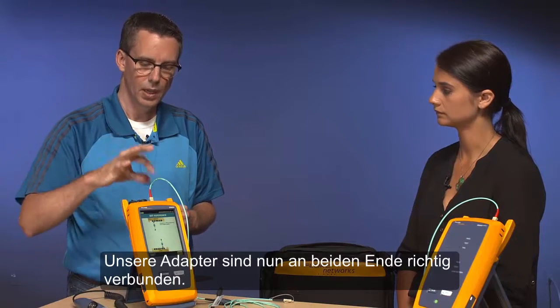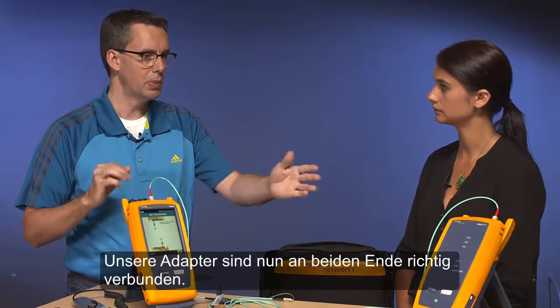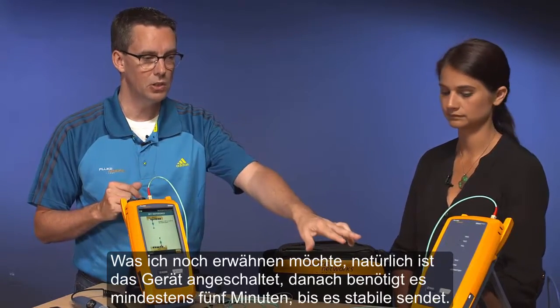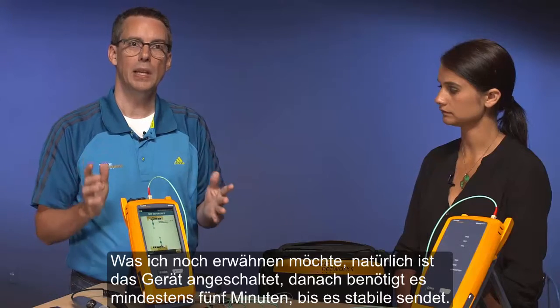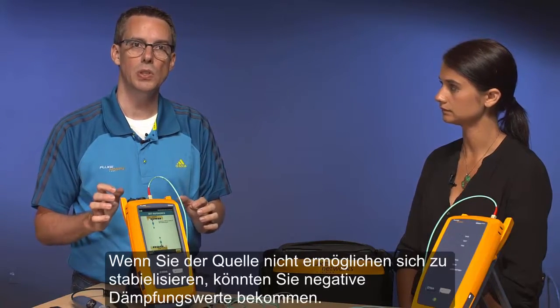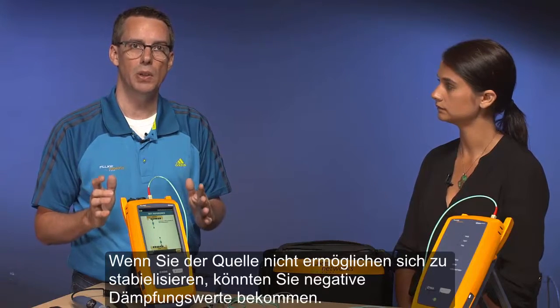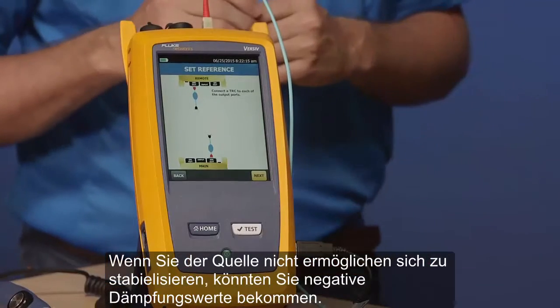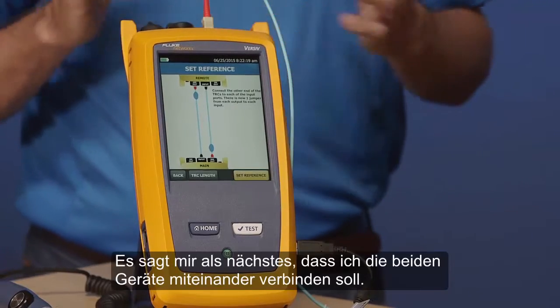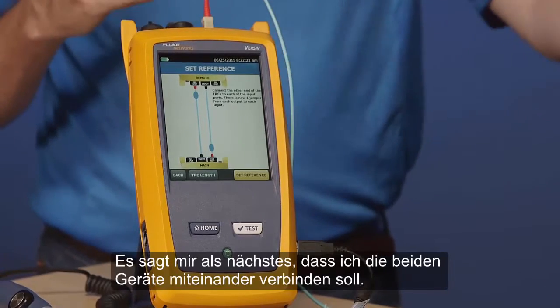So, our cords are connected to our outputs at both ends. The other thing I forgot to mention, of course, is that these instruments are switched on and they'd be left on for at least 5 minutes to stabilize. If you don't allow the sources to stabilize, you're going to end up with negative loss results. Okay, Amanda, go ahead and tap next. So the next thing it's telling me to do is I want to connect the 2 instruments together.